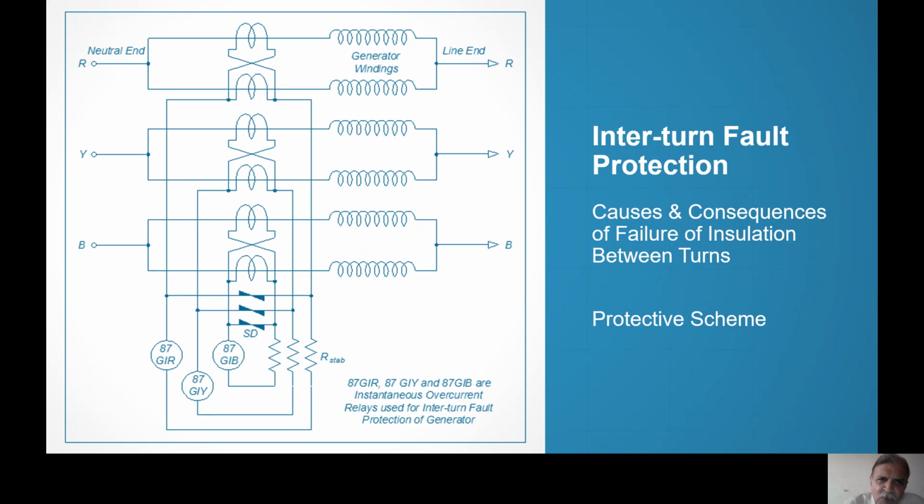Say 4500 is there; then in one of the paths, it will be 5000 ampere or more. It is a fault between two conductors of the same phase, so it will be a local hotspot, nothing else. So interturn fault is not dangerous to the generator. The generator can keep on running and deliver power, no problem.